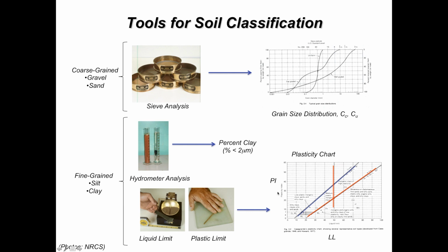And so when we classify soils using the unified soil classification system, we would plot the results of Atterberg limits in this space, plasticity index versus liquid limit. And there are various zones within this plasticity chart. You can see here is MH, so a high plasticity silt. We've got clay materials above this A line. The liquid limit of 50% differentiates low plasticity materials from high plasticity materials.